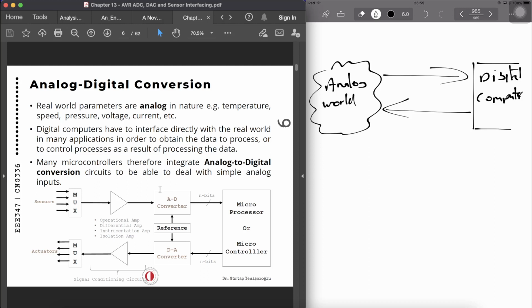So that's why we use MUXes, so we can direct a number of sensors into these MUXes, and we can actually choose which sensor or which channel we want to read. Okay, so we can read one channel at a time rather than having a separate unit of signal conditioning and then A to D conversion. That's why we use MUXes,